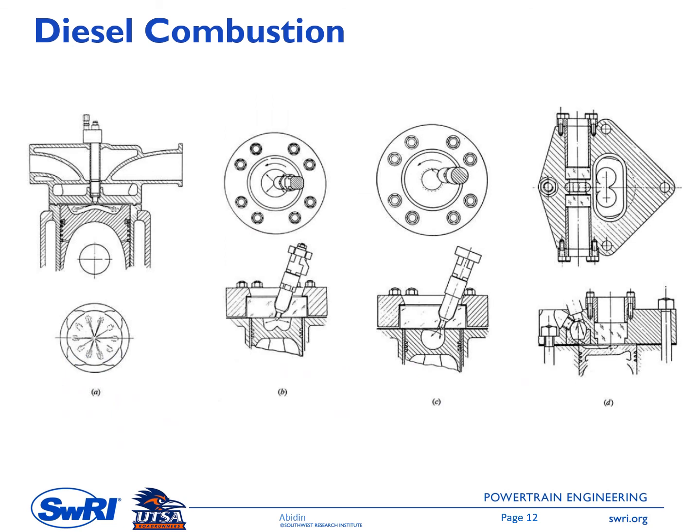This is showing the system that was used to record the flame on the previous slide. On system A, it is a quiescent condition, and it is a large engine with an open bowl, and you can see the schematic of the spray here. It has 1, 2, 3, 4... it has 10 nozzles here for system A, and then system B has a smaller nozzle number.